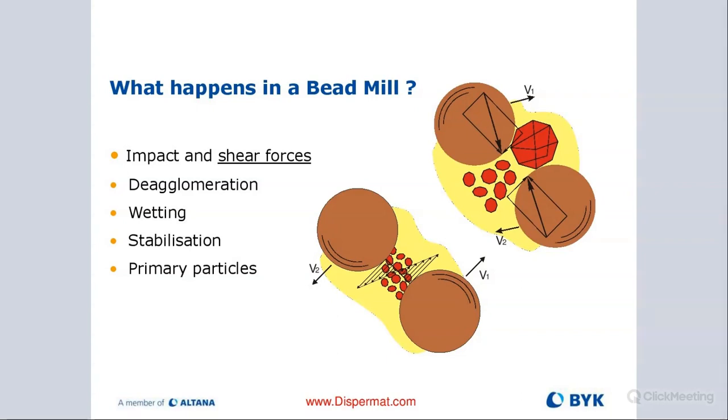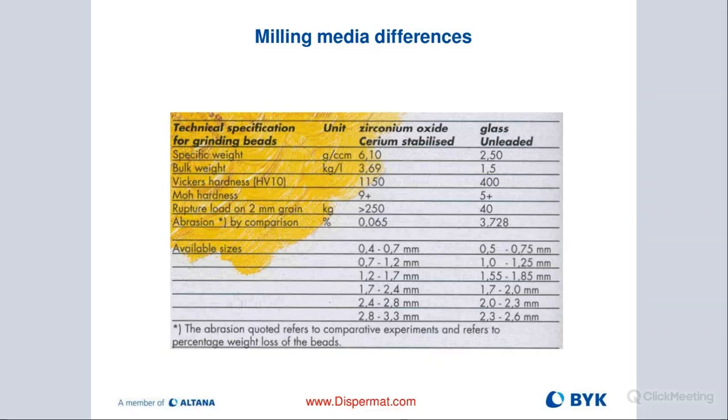So it's deagglomeration, getting the aggregates down to the primary particle size, wetting, and then again stabilizing with the right additive to make sure that they can stay in a suspended state.